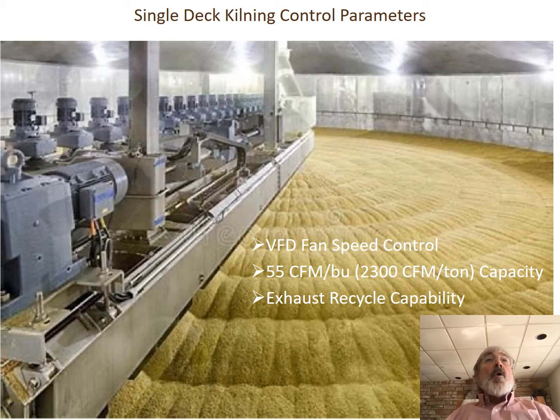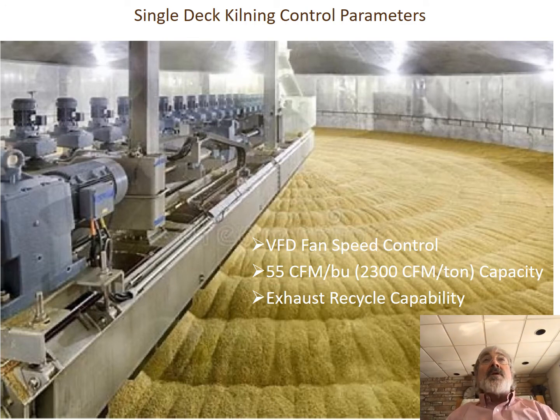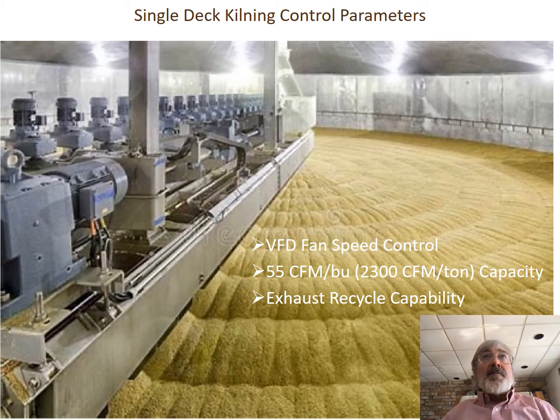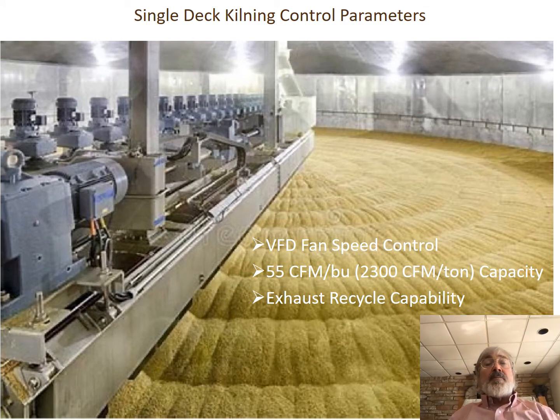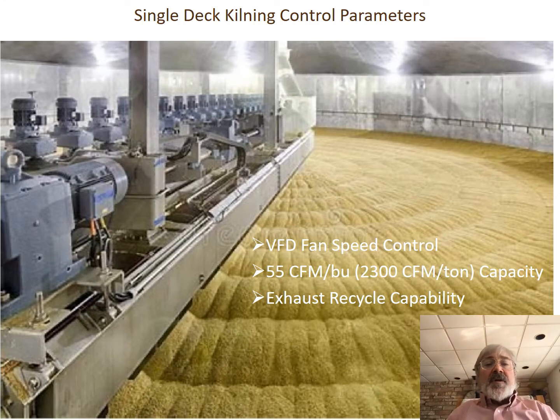Or you will run into problems with blowouts, which is where part of the bed just explodes, and then you have to shut down and fill that hole back up again. You can control the blowouts and measure whether or not you're bypassing using static pressure measurements, which is very simple. The other thing this has got is the recycle capability.